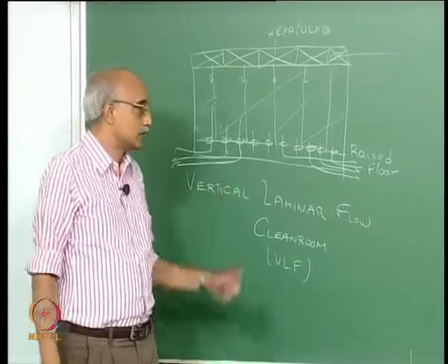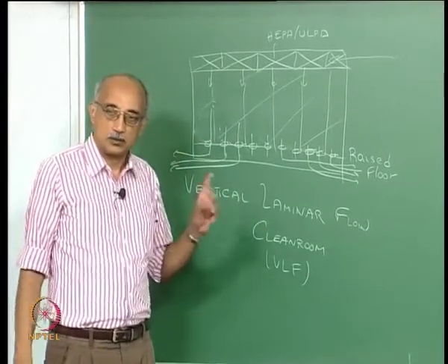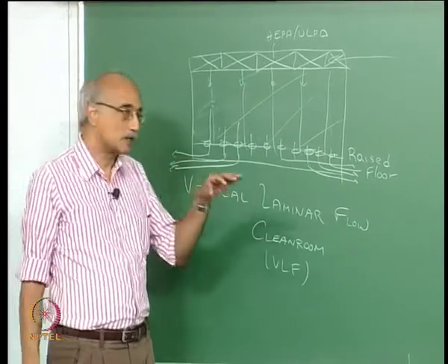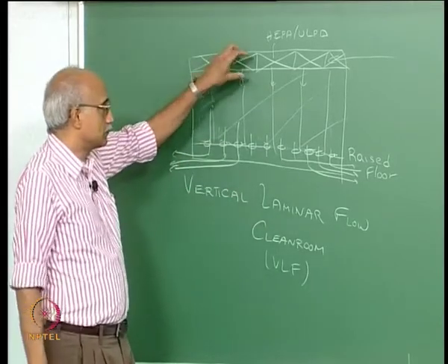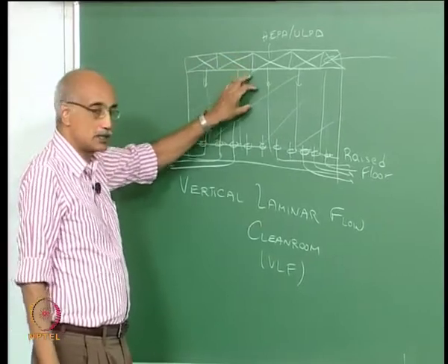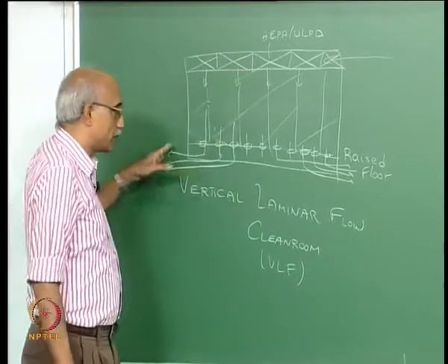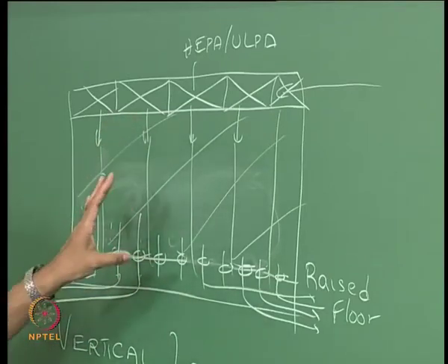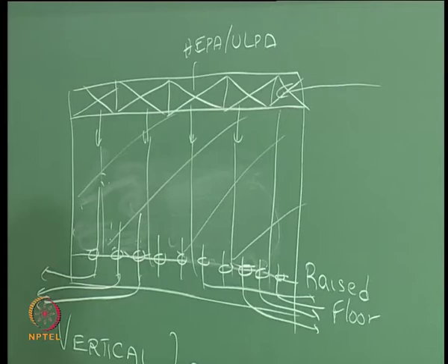In a clean room, you don't want turbulence to happen. You want all the airflow to be at high velocity and directed in such a way that it takes particles that are located inside the clean room and as quickly as possible purges them out of the clean room. So this is kind of the overall setup that you want to have.